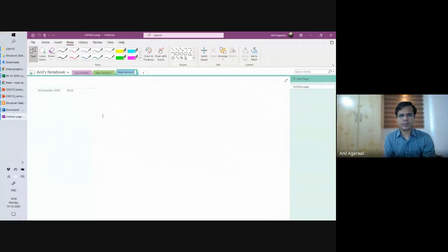This derivation I've taken from a textbook wherein the sign convention was slightly different from what we are typically used to. The moments that are in clockwise direction are considered positive here. I hope it won't be too confusing for you. This is a frame member. To start with, I'm assuming a simply supported boundary condition here. That means it cannot move in the lateral direction at the two ends, but it can move in the axial direction. Anywhere in between, it can move in the lateral direction.